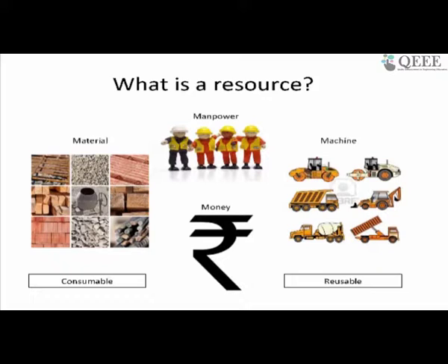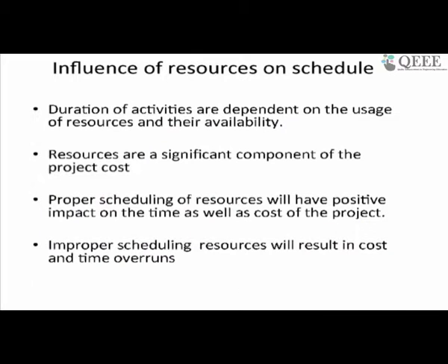Resource management becomes an extremely important part of scheduling or planning. Without resources, there's not much you can actually do, and if you don't manage the resources, you are not going to be able to manage. We have seen how the duration of an activity is dependent on the resource. The more resources I put into an activity, the duration could change, case to case. Those who have done crashing know that if I decrease the duration, my cost for each day might go up. But if my time is critical on my project, I can decrease the duration by increasing resources, which add to project cost.